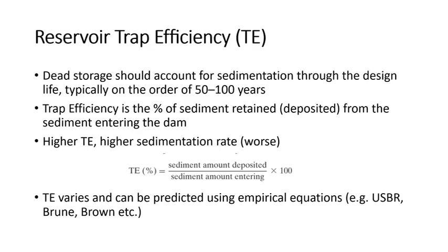Alright, so note that dead storage should account for sedimentation that is good for 50 to 100 years. So you are talking about 50 to 100 years worth of sedimentation when you're talking about dead storage of a dam.